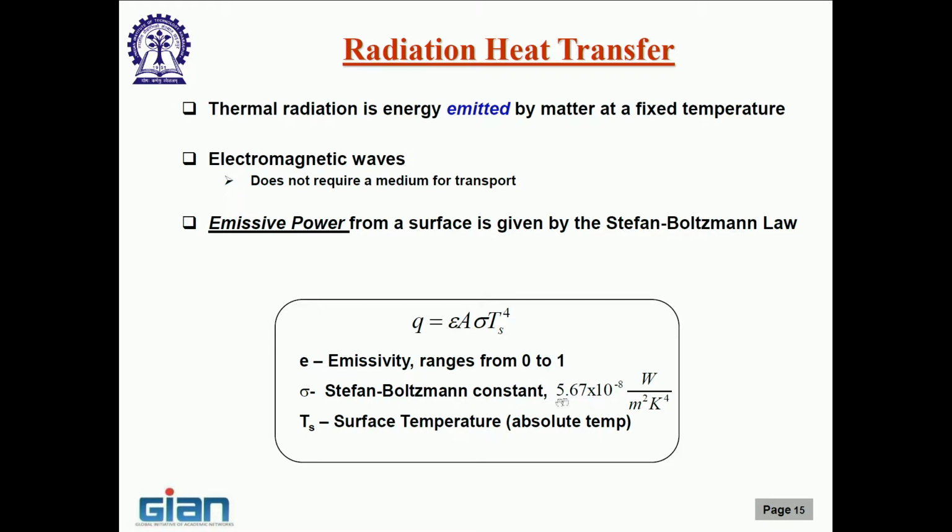Here you see the Stefan-Boltzmann constant. Okay. So, this is radiation heat transfer. For many practical applications, especially for computing products, this turns out to be a small contributor. However, if you are really talking about high temperature electronics, or where you are working on something under extremely cold temperatures, so that when the temperature difference is high, the radiation also becomes important.